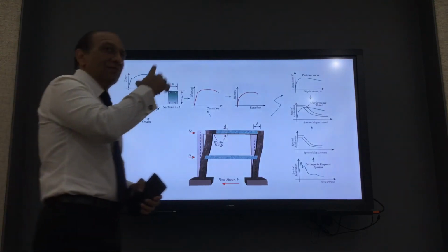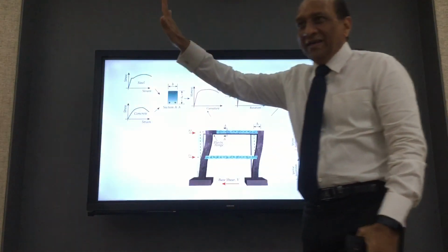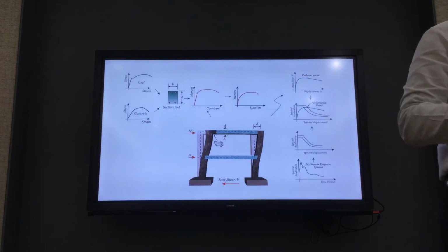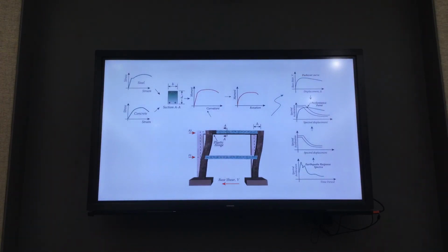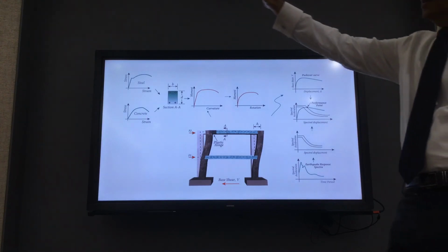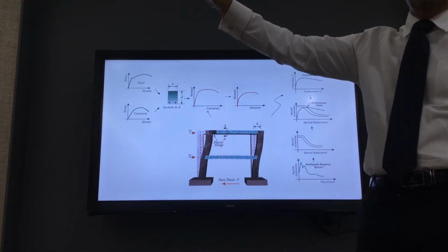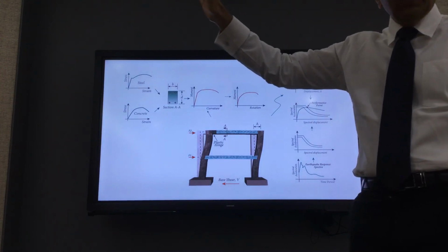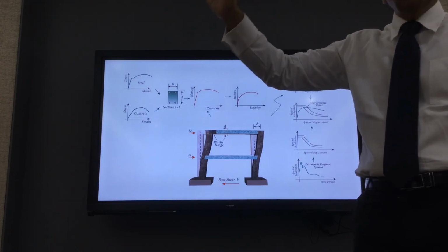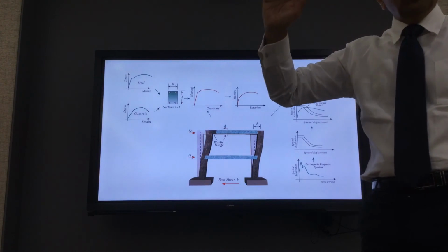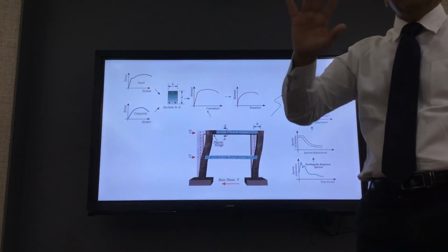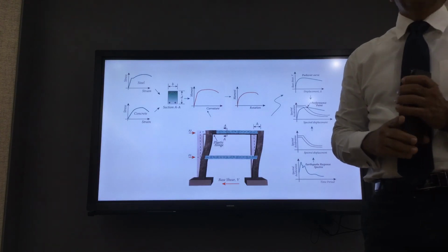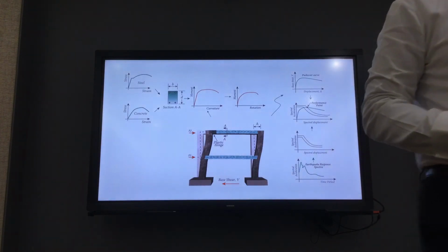And why in that building, one building got damaged more? It's a beautiful... I'm so sorry, I apologize. It's not a beautiful picture, but it's a very informative picture because there is one 17-story building, 12-story building, and 9-story building. And the level of damage is very different in each building, right? And it has to do with the natural period, it has to do with many things. So it's like a textbook case. If you look at that building, you say, oh wow, the theory really works. Unfortunately.